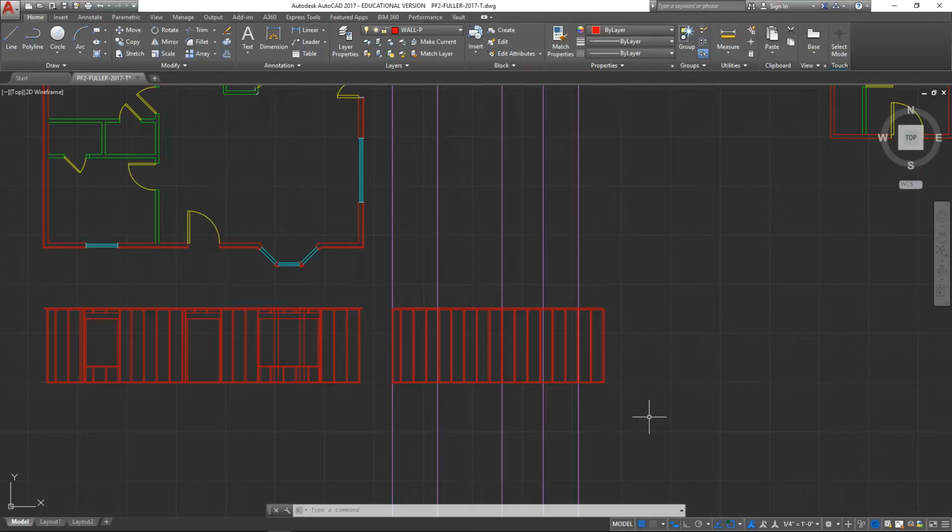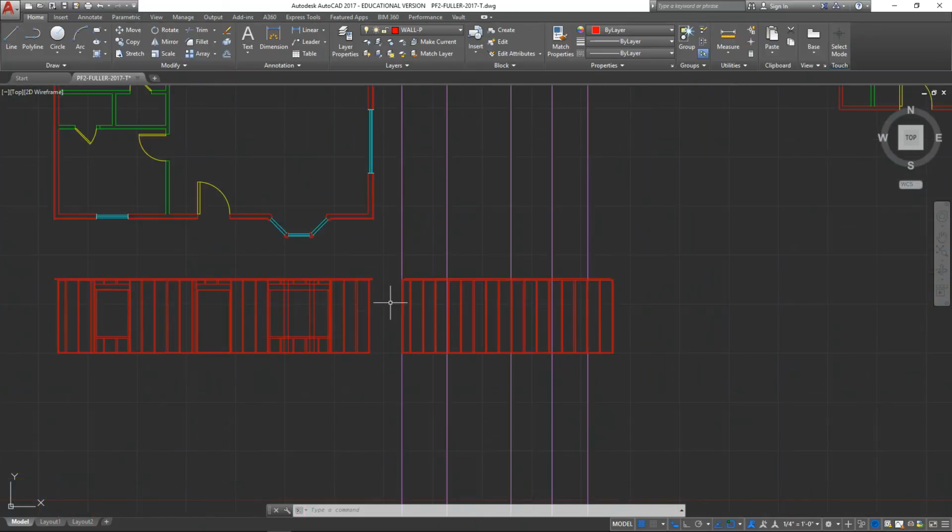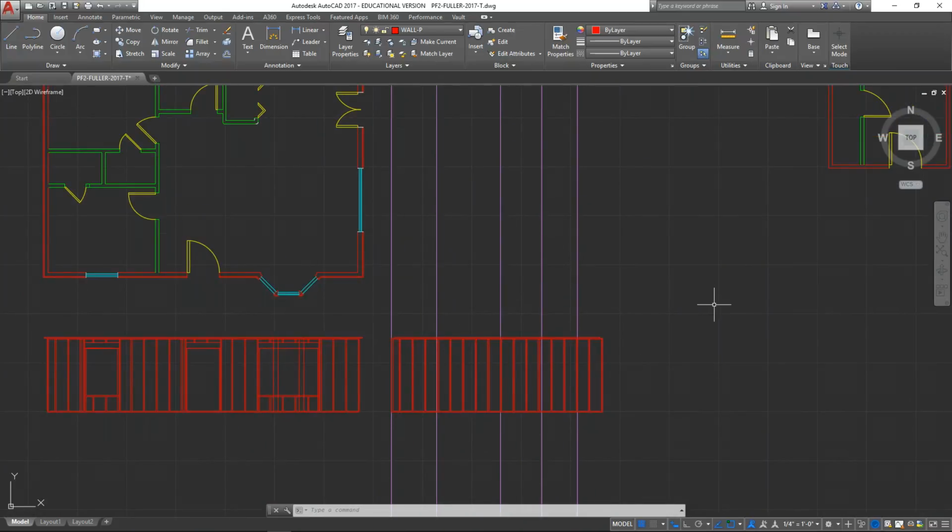Go ahead and get your wall built, your 2 top plates, and your bottom plate. And I'm going to show you here, this is how those walls will fit together, but they'll fit together at 90-degree angles. This top plate here will extend over this one, and they'll kind of help tie the walls together. Okay, so go ahead and do that. Go ahead and just make your wall, distribute your 2x4s, and make sure everything's all nice centered, 16-inch centers, and there we go.